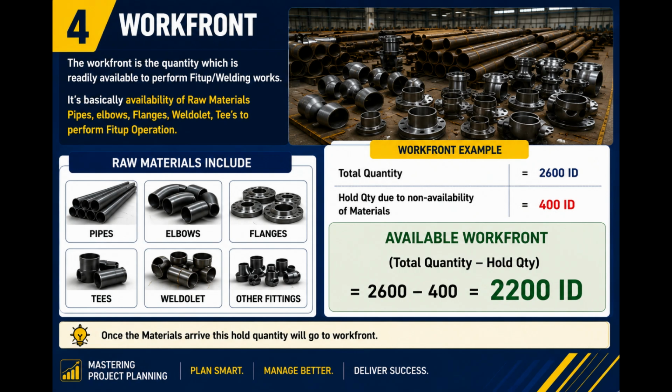Then the drawing also has to be in the IFC stage, so it has to be approved and issued for construction purpose. Then for this we may also do spool gen, like weld map drawings. In the isometric drawing, we'll be putting some weld joint numbers. If it is a fillet weld, there will be separate tag numbers we will use. Sometimes there are support welds like a reinforcing pad to be welded on the pipe, so then the joint numbering will be different. In one of our earlier projects we used T1, T2, or you may also call the reinforcement pad RP1 or RP2.